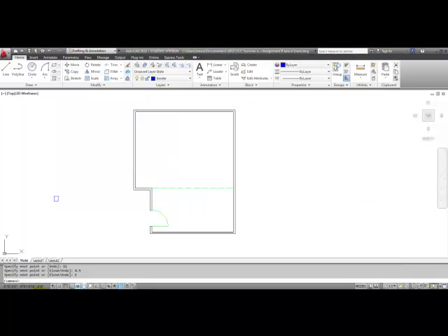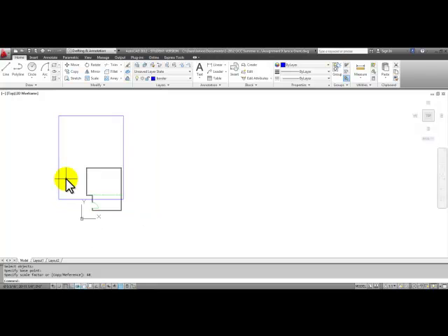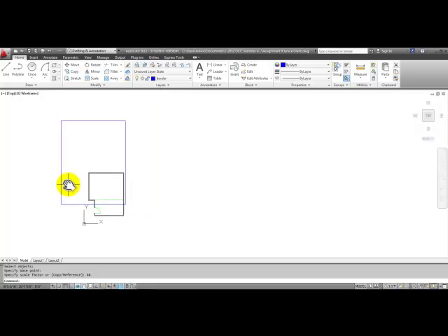So going back to our drawing, we can use the scale command to scale this small sheet of paper 48 times the size. In the modify panel, select the scale command, select all 4 of these lines that make up your small sheet of paper, and then enter. Pick a base point that's close to this sheet of paper at the bottom left corner. Type in 48 and enter. You'll notice that that small sheet of paper now is 48 times the size.